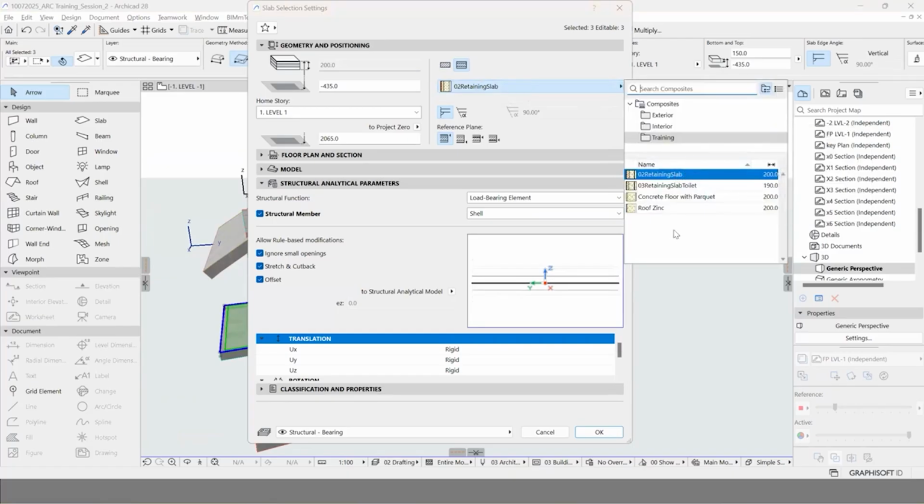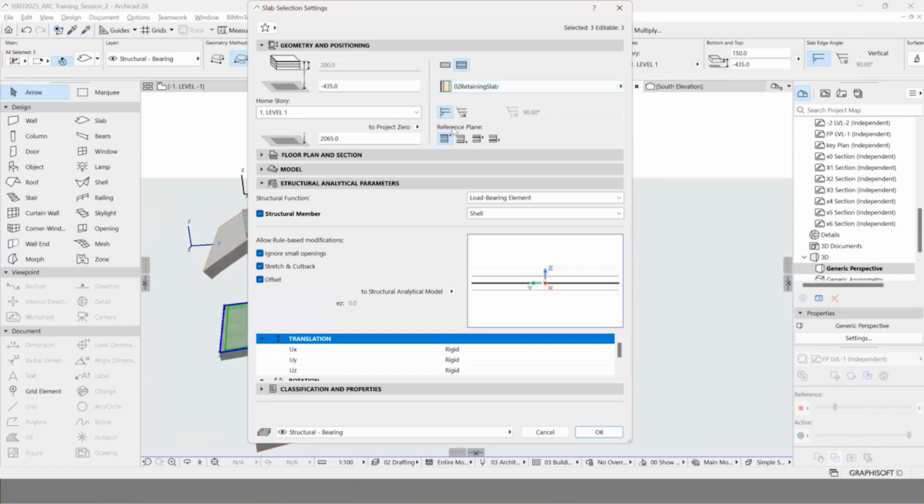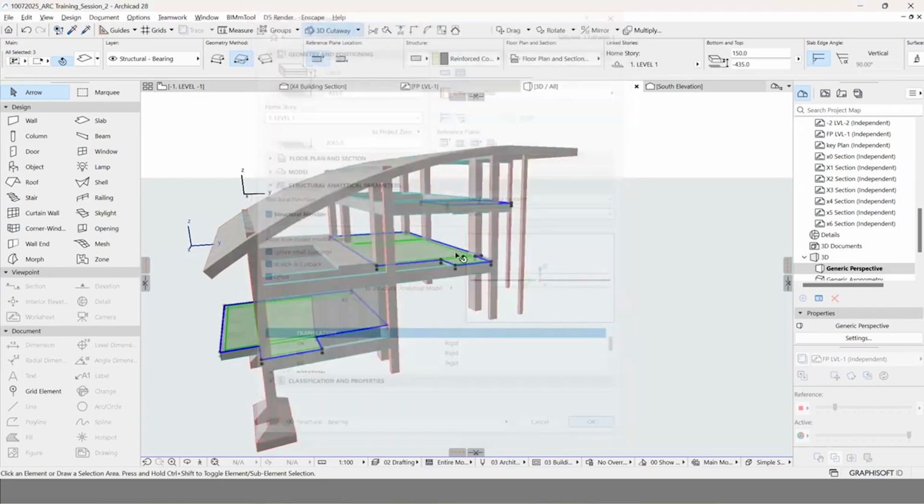This is something that I just created for this. And the reference plane is the same as for the wall, if you remember: outside face, inside face, core outside, core inside. But for the slab, it is top or bottom. I need to use the core top because I also have finishes and I want to maintain the core where I have given the lines for the reference. I'll give OK. Now you will see those layers have been added.